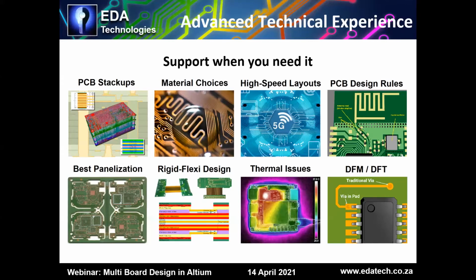Look, it's not going to replace going to, say, for instance, ICAS and getting certification there. But instead of having to pay for the full test that they do, and then you get back and it's like, oh, your board failed, and then you have to go and respin, we can do a much lower cost quick scan, and we can say, okay, your board is likely going to fail because there's a high spike in this region of the board on this frequency. You might want to have a look at that, address that.